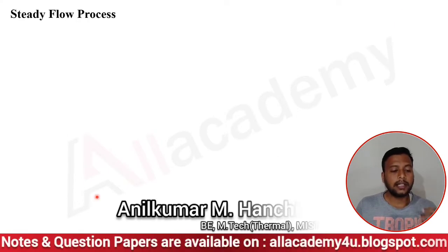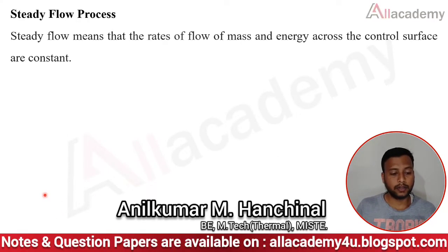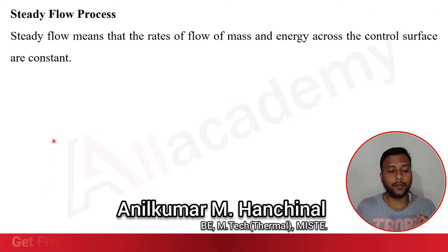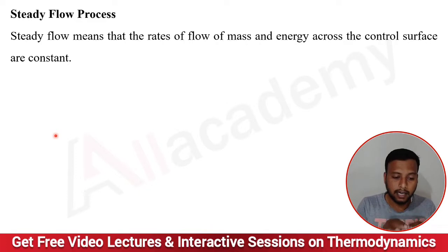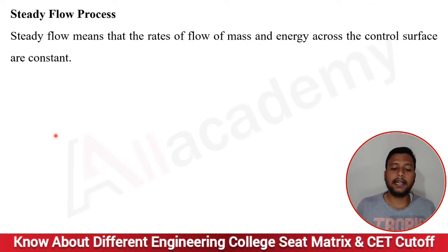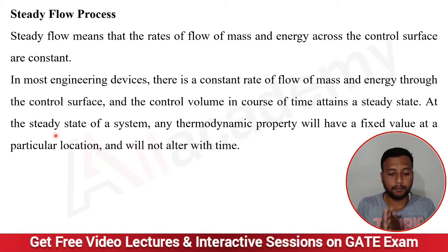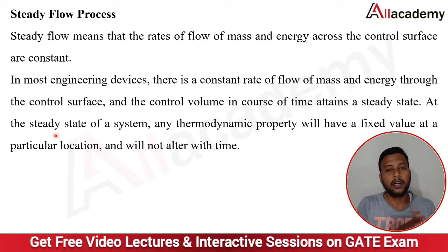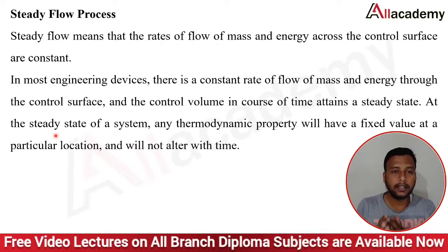Now what is this steady flow process? The steady flow process, or steady flow, means that the rates of flow of mass and energy across the control volume are constant. Whatever the rate of flow of mass and energy across the control surface is, that is constant.